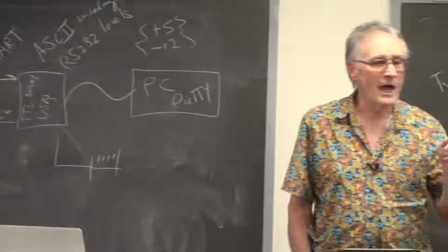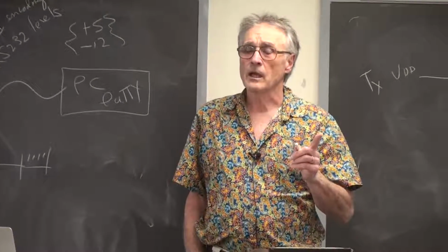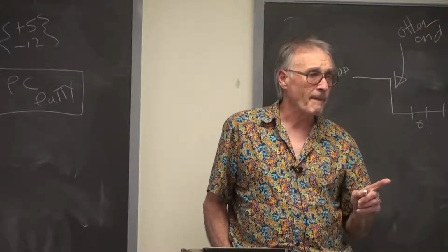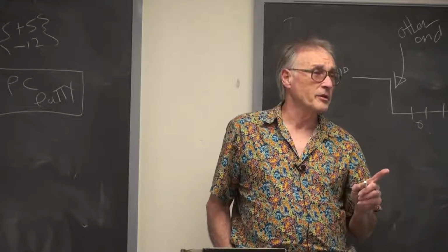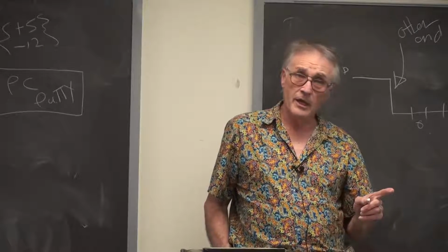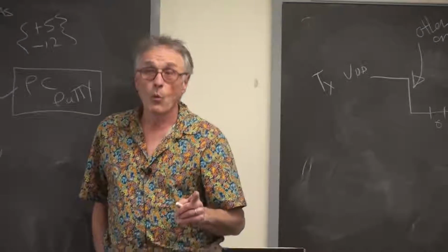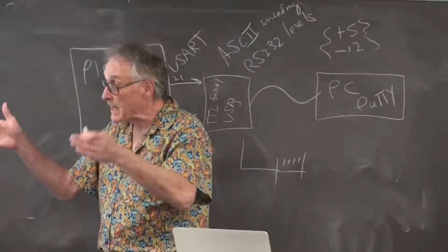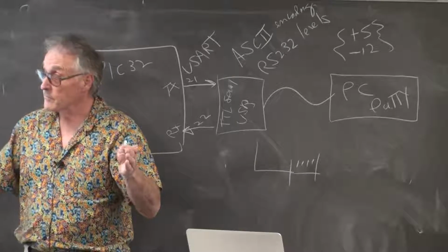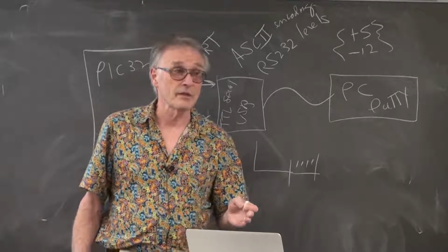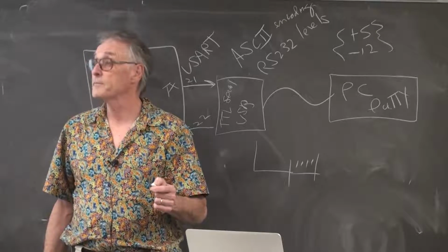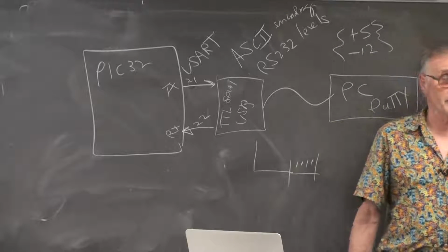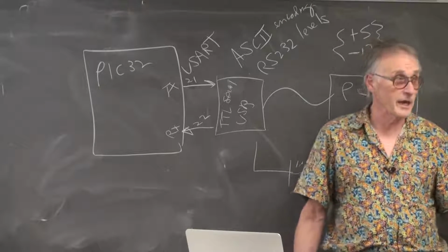Because there is no clock transmitted, if we're going to have 10 bits, each one of which is sampled 4 times, the maximum clock skew between the transmitter and the receiver cannot be greater than 1/40th of the character time, because that's the number of sample times within the character. Therefore, the clocks have to match within 2.5%, which is 1/40th. And as you know from Lab 2, the internal resonator is good enough to do that. It's actually 0.9% or so.